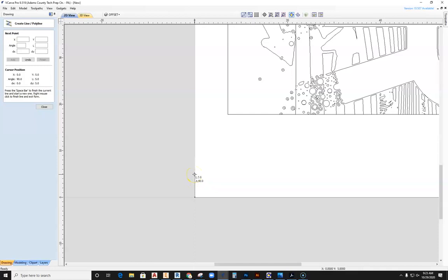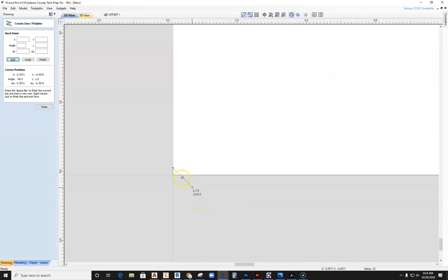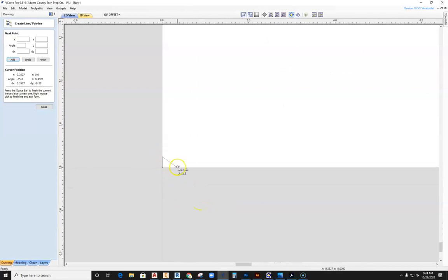Now, to center the sheet in the Y-axis, we have a 47.5 size sheet, and we have a 48 size stock. I can come up and push this thing up by 0.25, and I type that in on my computer and hit enter. That has given me a little teeny tiny line down here that is 0.25 long. Okay?